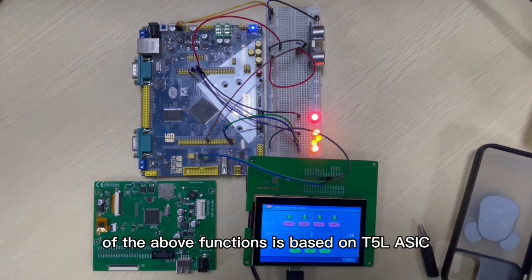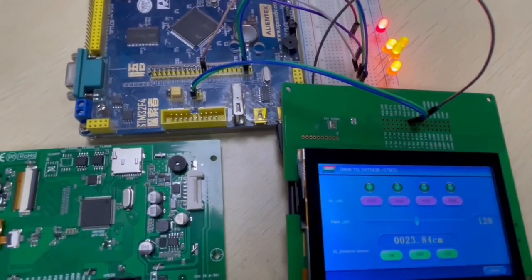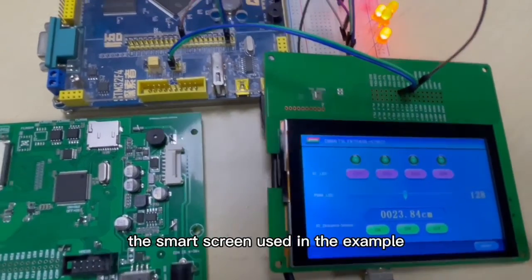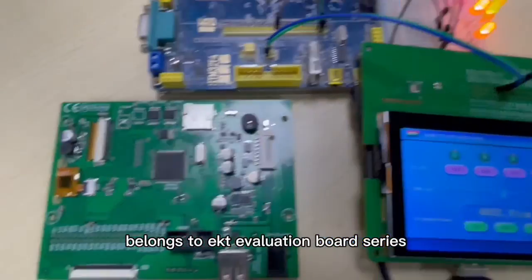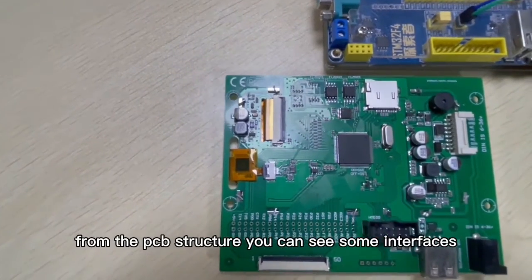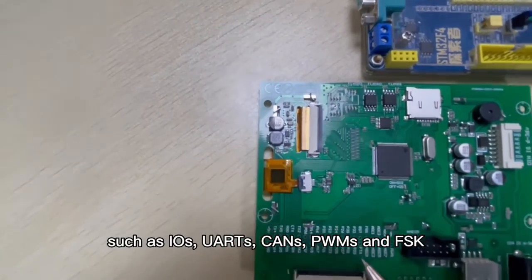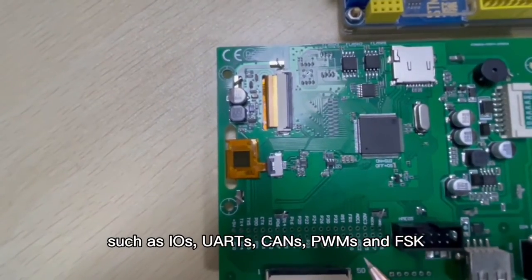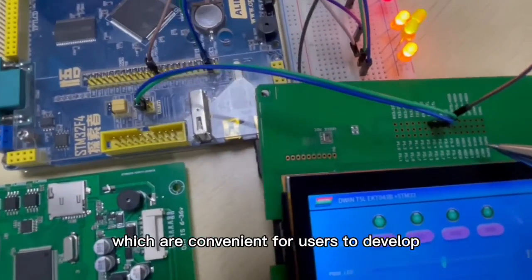The development of the above functions is based on T5L ASIC. The smart screen used in the example belongs to EKT evaluation board series. From the PCB structure, you can see some interfaces such as I/Os, UARTs, CANs, PWMs, and FSK, which are convenient for users to develop.